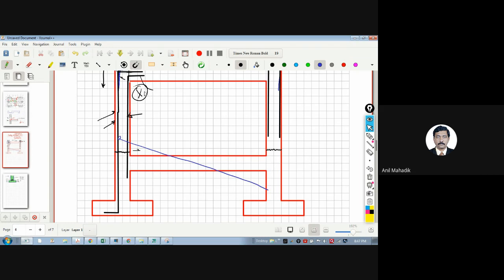And in the column also there will be big bending moments and a huge shear force. So at this zone there is a huge shear force and huge moments due to the earthquake, and we are creating a cold joint, construction joint or weak plane there. So we are telling it to fail here. This is very much not expected. That's why the column starter is not recommended.